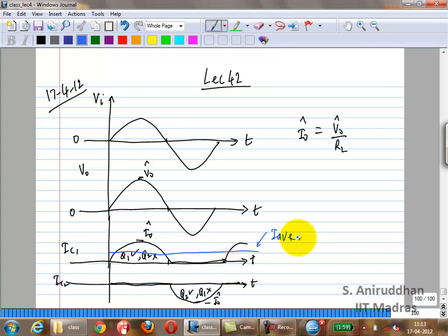And because the current is varying as a function of time, you can define an average current, which you can call the DC current. Even though there are cases when the transistor is turned off, you can define an average current, even though you may not be able to define a well-defined quiescent point which is valid for all time. Why are we interested in I average? Power dissipation, right? Because I average is the current flowing from the positive supply to the negative supply. So the power drawn from the supply will depend on I average, right?